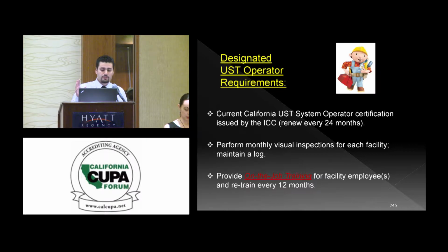This also verifies the fact that, if there's a cold start, if you guys are familiar with the term cold start, essentially all the memory from the monitoring system panel is erased, so all the setup is gone, and they have to go back in and reprogram how each sensor works. And when that happens, we have to go out there and verify that what they programmed is still doing what it's supposed to do.